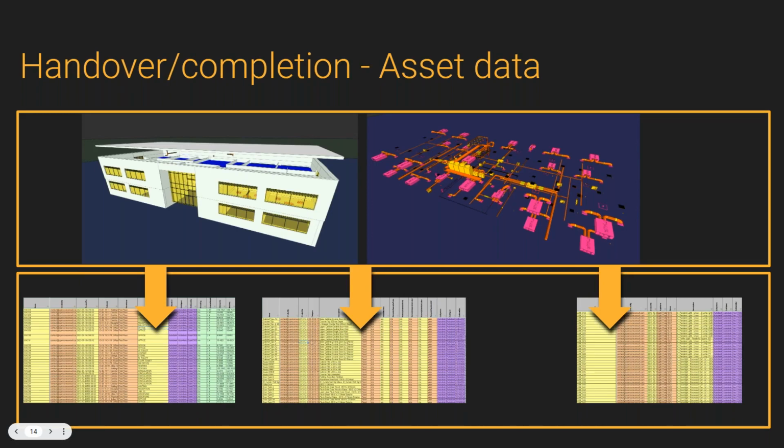And then finally, we've got validating and extracting your asset data at the end of the project. So again, the example here in front of us is COBie data. For that, you can use the Solibri extension that's available. So that will actually validate and give you the Excel or XLS reports that you need to hand over to your customer. But crucially with Solibri, we can also construct our own takeoffs. To give you an example of that, I've been involved in manufacturing projects where we've had bespoke BIM data in there. There's been specific codes and references that relate to existing maintenance manuals, inventory systems, and that kind of thing. So being able to build an information takeoff rule set for that is something that's quite advantageous using Solibri.